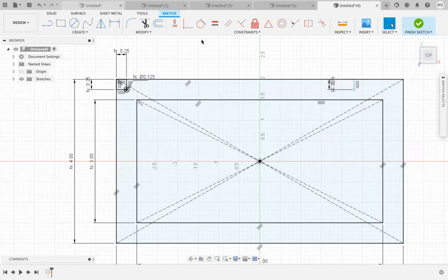And now this line is partially constrained. The line itself is locked to the outer edge. When I hover over here, you can see that little coincident constraint. It tells me when I click on it. Even when I hover over that coincident thing, it's telling me it's this line. And you see the top edge is blue. So it's telling me exactly what's coincident. The length is locked in, but it's blue because I can slide it anywhere left and right.